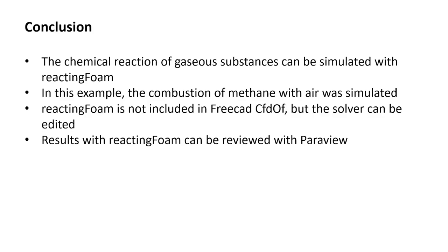Let's come to the conclusion. The chemical reaction of gaseous substances can be simulated with reactingFoam. In this example, the combustion of methane with air was simulated. reactingFoam is not included in FreeCAD CfdOF, but the solver can be edited. Results with reactingFoam can be reviewed with ParaView.